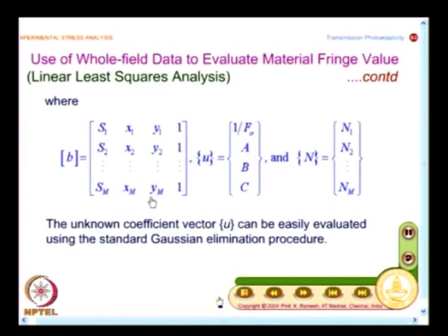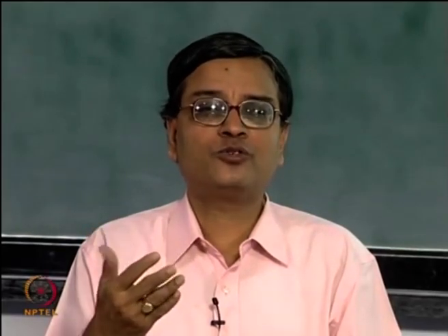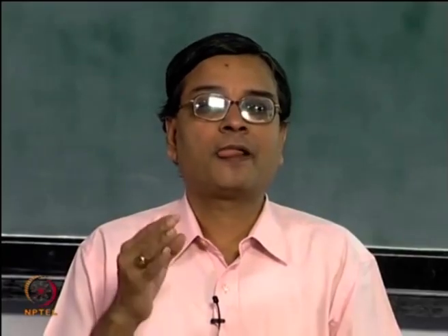And from an experimental point of view, I can determine them conveniently if I have a digital photoelastic approach, but even manually you can do it. In fact, I have one of the assignment problems where I have a circular disc under diametral compression with the fringes, and I would expect you to extract these data manually, so that you appreciate the advantage of a digital photoelastic approach. You can also do it manually, you can also do it by digital photoelastic approach.